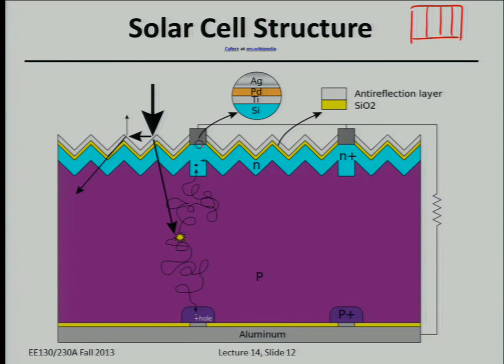The metal, the electrical conductor, is opaque, so you want to minimize the surface area occupied by these metallic conductors. That's why they're skinny little lines, right? Because you don't want light shining on the solar cell and reflecting back. Anything that's shiny is reflecting light back at you. On the back side, it doesn't matter, so it's usually a complete metal layer there, because light is only shining in on one side.